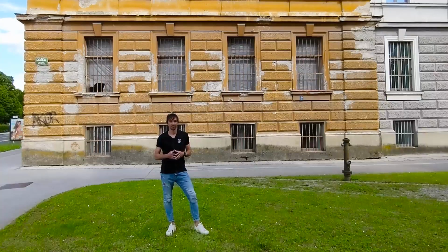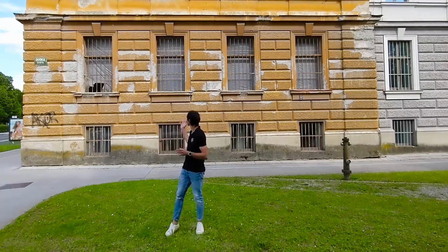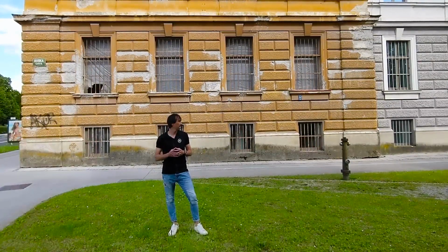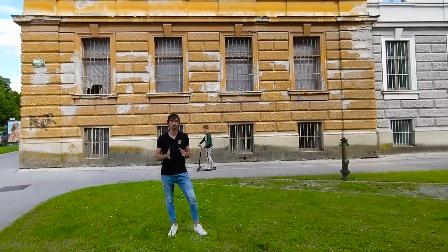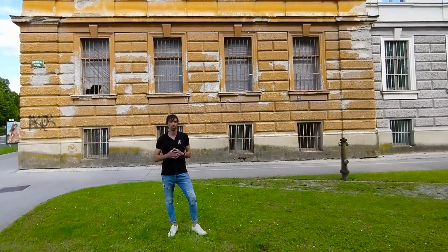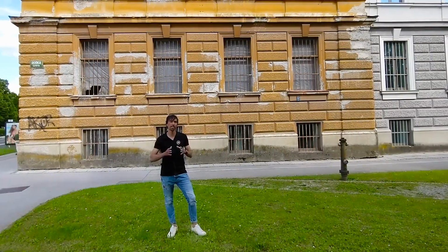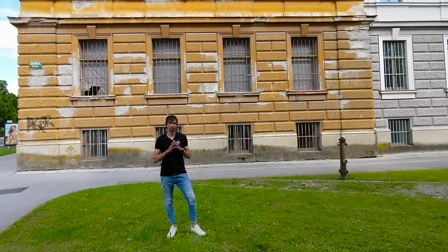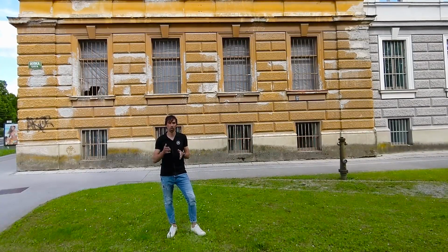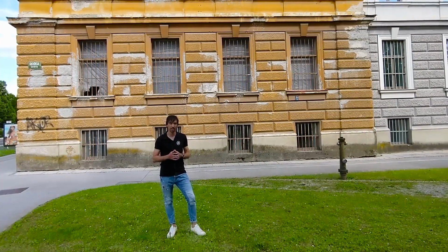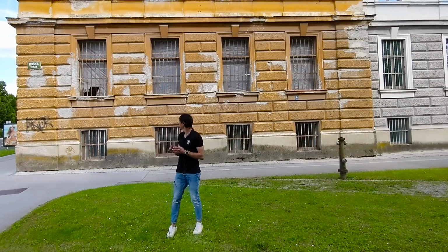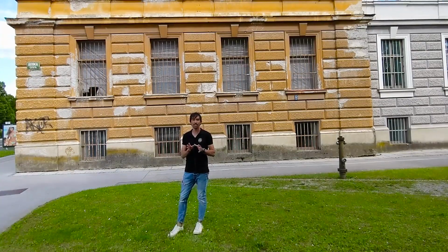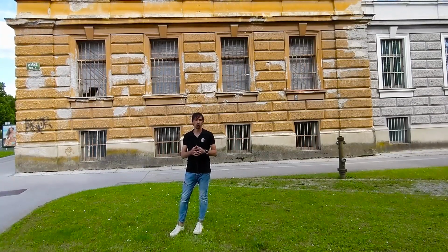Okay, behind us is a super nice old building, which is a cultural heritage building, and they will start with restoration works. Before they do the restoration work, we would like to document the complete building with all the building facades in high detail. We would like to produce an orthophoto with a resolution of 1 millimeter and a textured 3D model with all the small details, which are super important, and have them documented in 3D to do the restoration work properly.